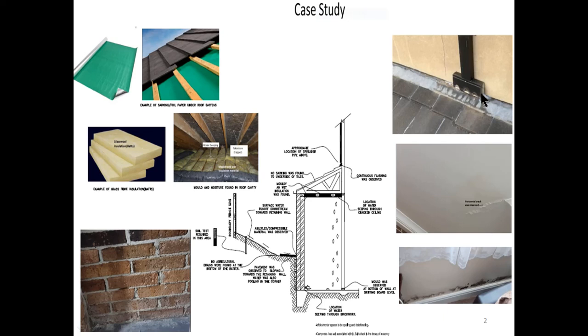To quickly recap what we have covered in part 1. We observed water ingress through the lower roof cavity, and further to this, water was also seeping to the underside of the garage brick wall. Unfortunately, we had to deal with two separate issues here. We also discussed the main observations made during the site inspection, such as wrongly installed upper load spreader, ceiling plaster crack, moldy skirting boards, moldy insulation, and deteriorating brickwork. In addition, we didn't notice any sarking paper under the lower roof battens.